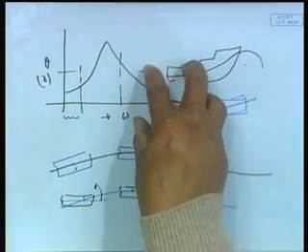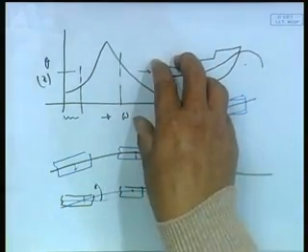Where inertia is dominating, typically my exciting moment and my response are out of phase with respect to wave slope, and as a result when water is rising, the ship is trying to go down. In this case the bow is going to go down when the water is rising. Okay, so here there is a phase gap.